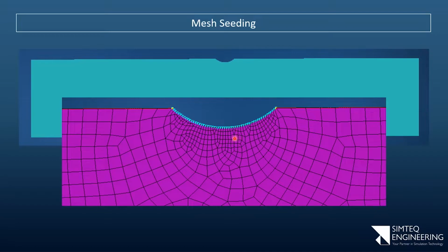The disadvantage of this method is if I look in these regions, I see pretty ugly elements. In these regions, they're kind of okay, but the elements just behind it are actually not that good. And this is exactly the area we're interested in. So we need to try and move these elements further away.